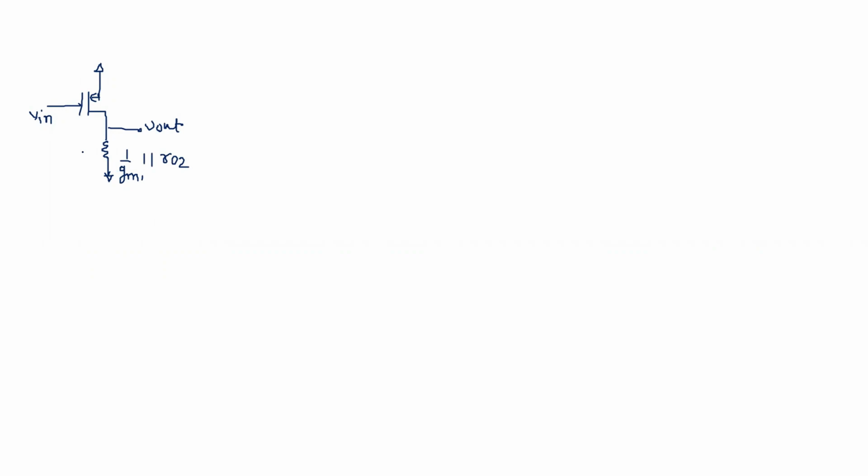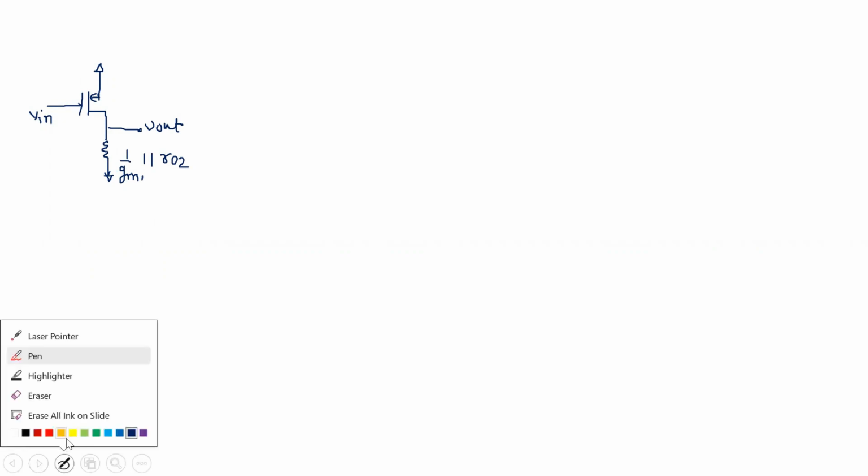And overall, if we are looking from this, okay, this thing is actually not parallel right now. Later, if I extract this resistance from M2, then it will become parallel. For now, this is only GM1. So this is 1 upon GM1. So this M1 is replaced by its impedance, and this is your M2. So this R out is inside this M2.